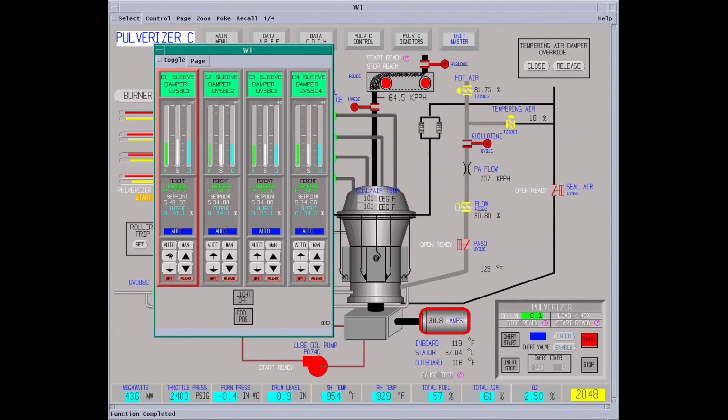All the sulfur is removed with a Trona product. We call it DSI, dry sorbent injection. It's using Trona. It's ground fine, sprayed in right before the air preheater, and absorbs all the sulfur. All the mercury is taken out with activated carbon and other stuff added to the coal. So mercury is very, very low.